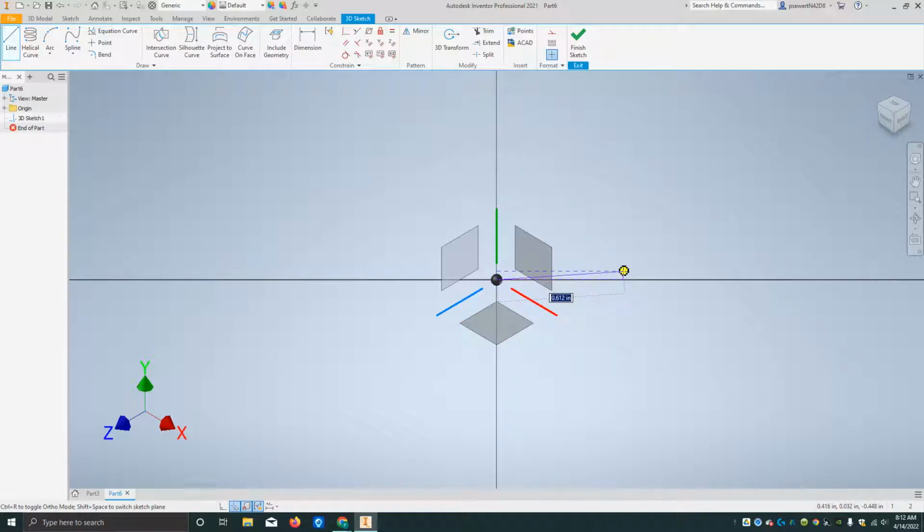Okay. The next thing I want to do is, and this is number 4, letter C in the book, I'm going to put the cursor in the X direction, and you can see the origin right here on my UCS icon, and you can see that the red axis is the X direction.